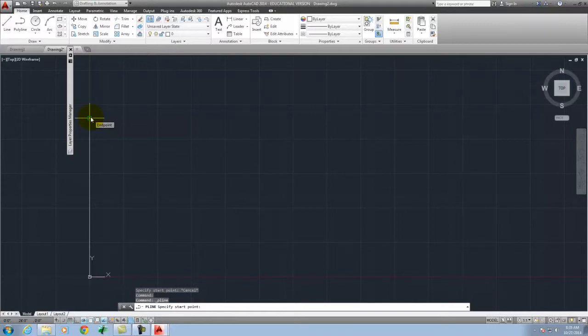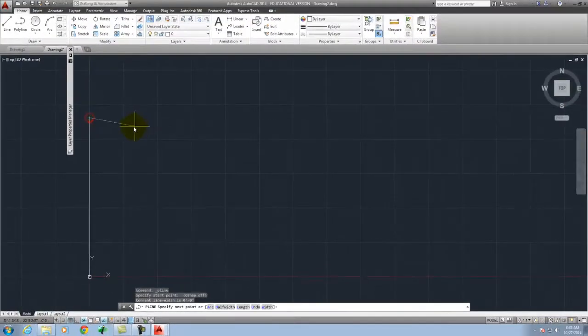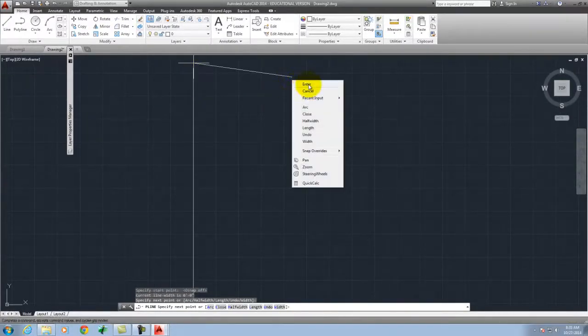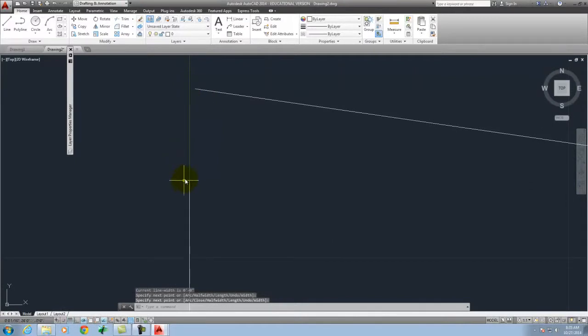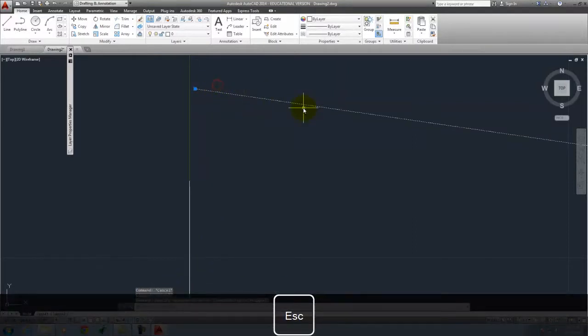And so if I didn't have it on, you don't have to do this, I'm just doing this for an illustration here, and it didn't show up, I'd say, oh, okay, well, I'll just start close to this. So I did it with the mouse, and I'll start close. However, if I zoom in, let me just go ahead and draw a little line here. The closer I get, the more I realize that these two points really aren't on top of each other. Let's see how far apart they are. They're 5/8 of an inch apart. Those are the kinds of errors that we don't want to see in AutoCAD.